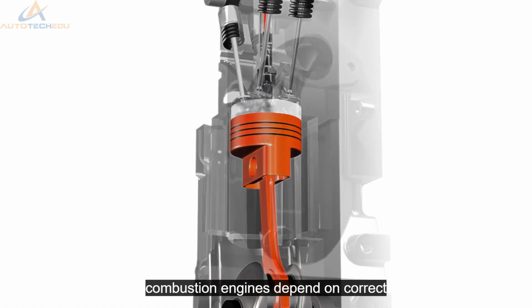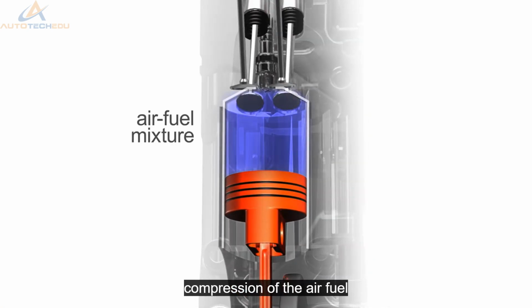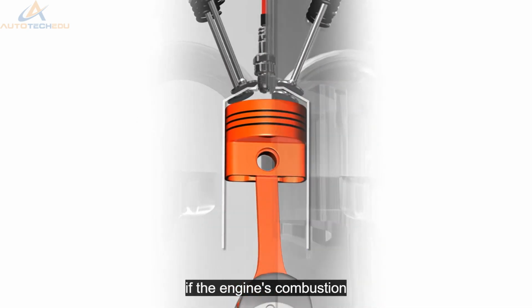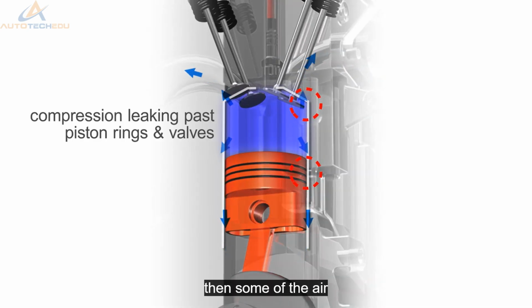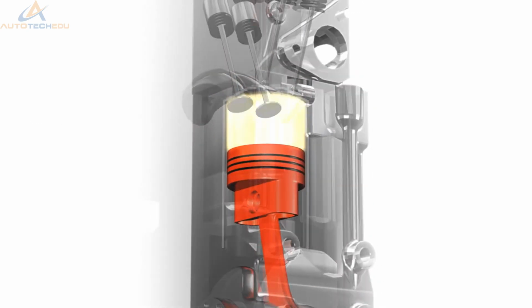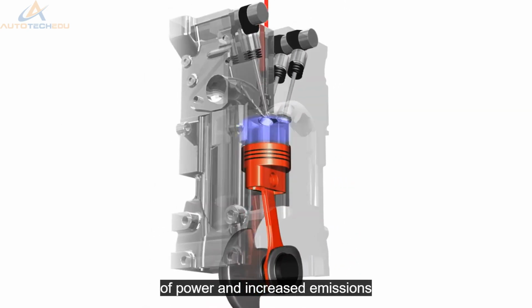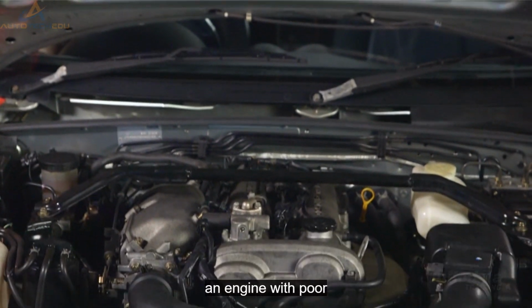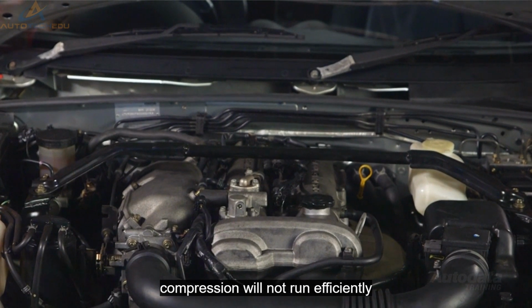Internal combustion engines depend on correct compression of the air-fuel mixture to maximise the power produced by the engine. If the engine's combustion chamber leaks, then some of the air-fuel mixture will escape during the compression cycle. This results in a loss of power and increased emissions. An engine with poor compression will not run efficiently.